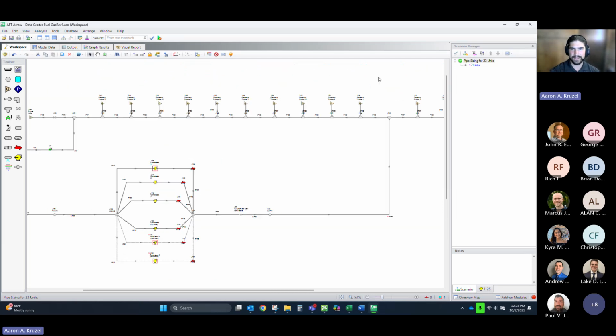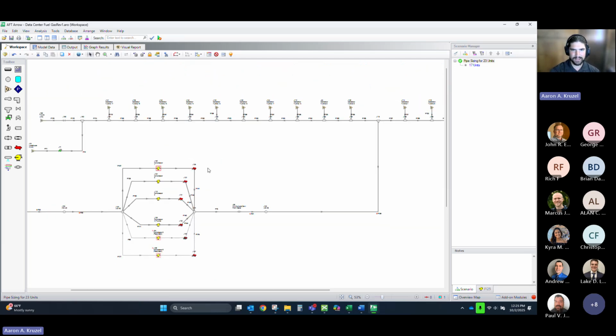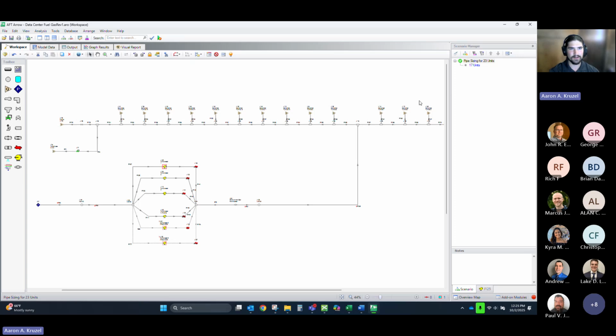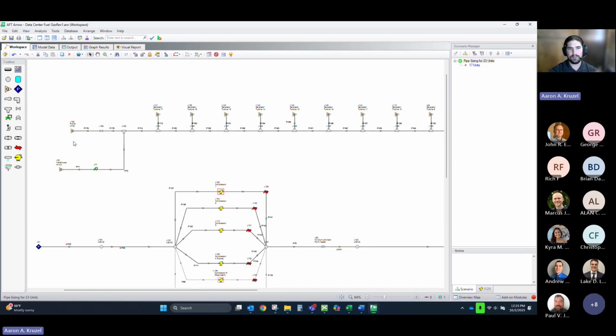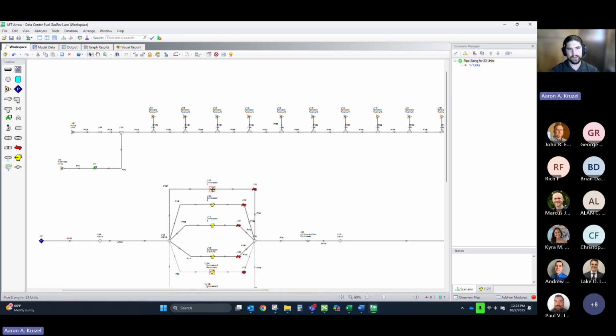So let's say you had this entire system. This was already an existing plant. So you have, I think, 17 CTs operating. But let's say you want to add more. We have some future units accounted for. How much more compression do we add with 3 compressors that are already sized and fit to a curve? Let's add another, size it, and then you can actually know how much horsepower you need for this compressor. It adds a really useful ability to have retrofit accuracy.